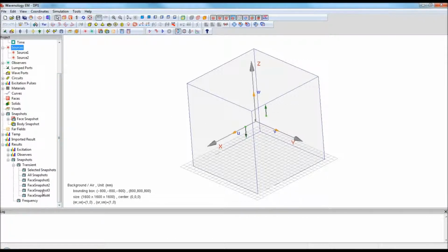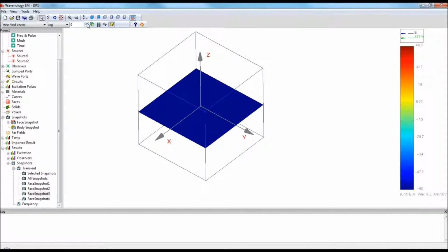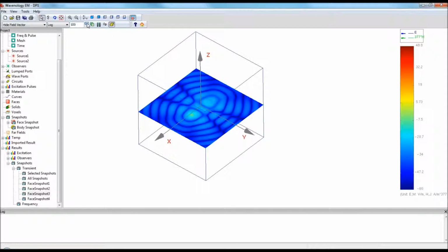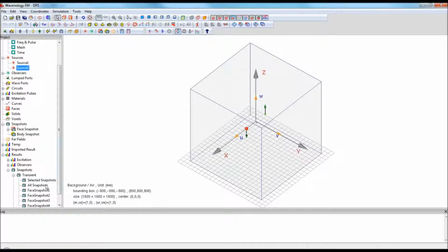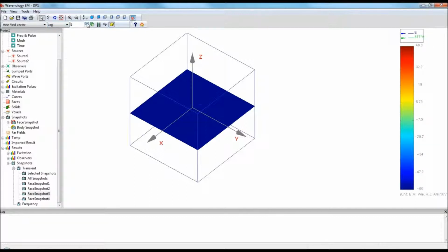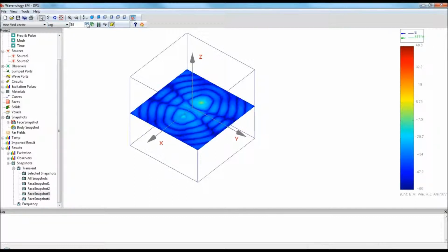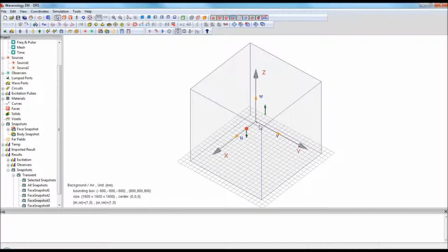So after the simulation, I can show the phase cut in this way. And if I use a log, you will see that the two dipoles are radiating at different phases. One is at the strongest, the other is the weakest. The way to achieve that is through adding the delay. I'm using a sinusoidal source at 1 GHz to radiate the field. By doing that, we can achieve all kinds of configurations of the two radiation sources. As you can observe, it's just radiating. All right, that's how the transient field looks. So that's about the dipole source in 3D.